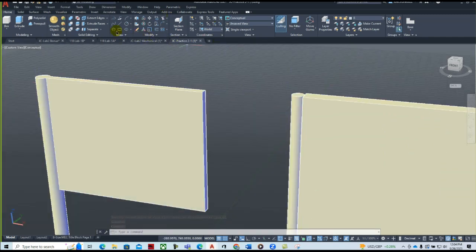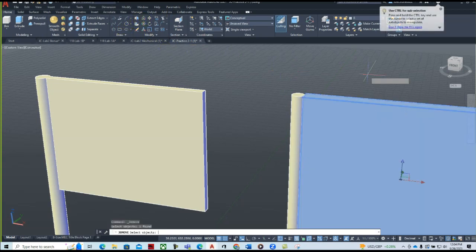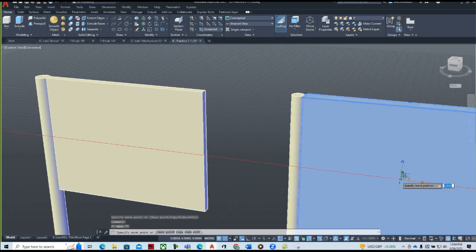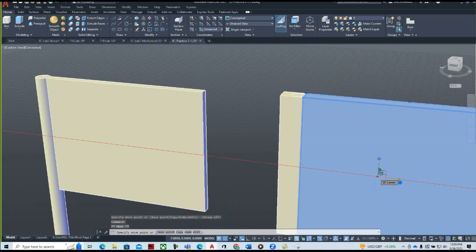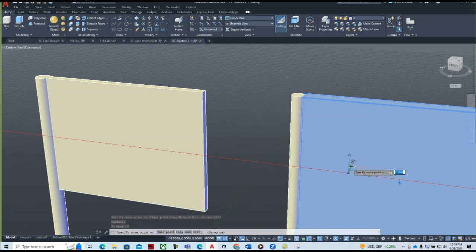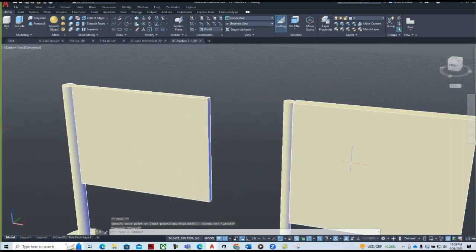And so what I would do is I would use a 3D move command. I grab it, hit enter, and then you grab one of the planes and you can just push it just by eye. And it's O-snapping with my O-snap, so I gotta turn it off because I'm just using a 3D move and it's fighting with each other. F3, thanks. Yeah, it's still goofing around on me.